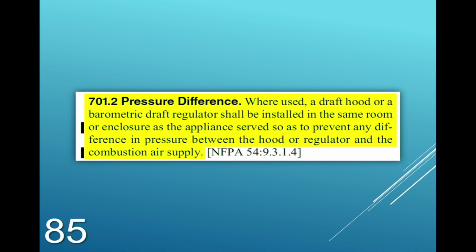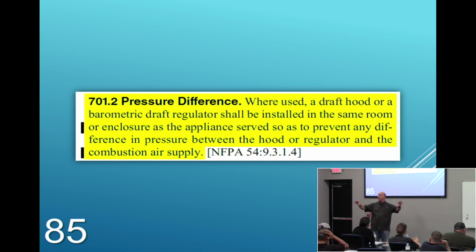All they're saying is, I don't want you to push or pull air to or from somewhere else. If this is my mechanical room, I have my fuel burning appliances in here, I'm going to size the combustion air for this room. So don't push air out, don't pull air in from somewhere else, right? If you got a draft hood or a barometric draft regulator, put it in the same room as the equipment it serves. We've already taken that into consideration now, right? I don't want you to push or pull air to or from somewhere else.